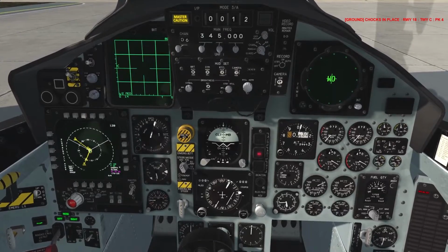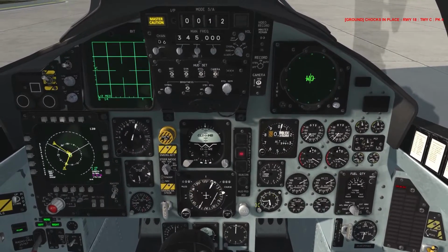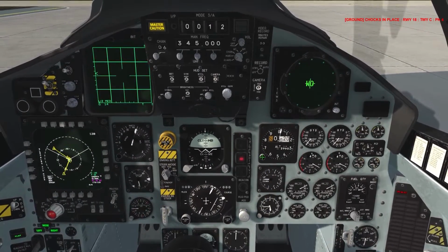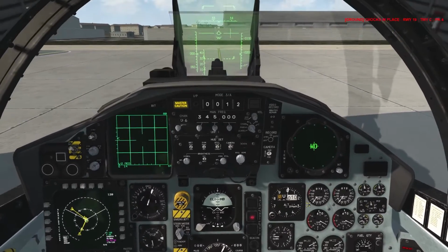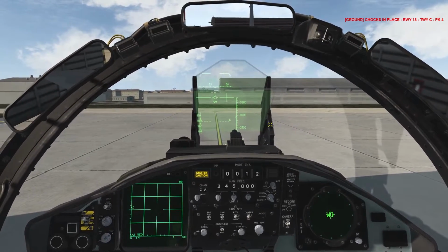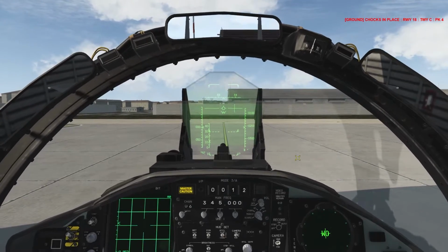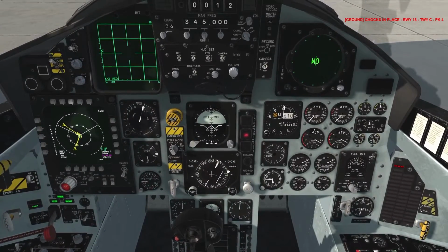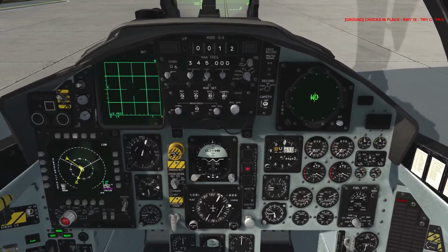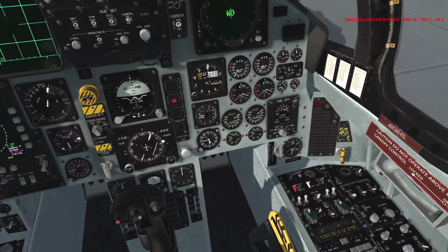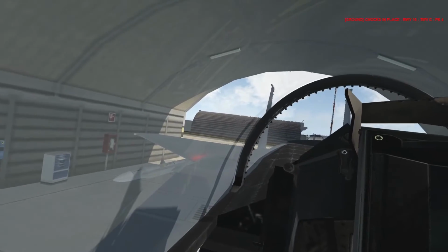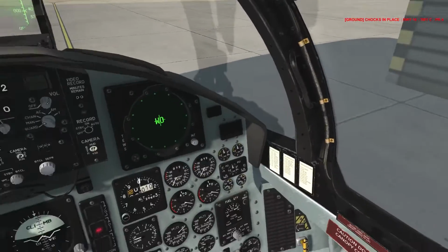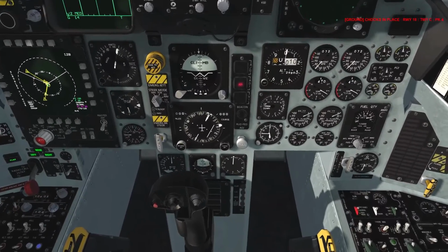Where are we? So altimeter's set. In this current build, maybe fixed before release, we do have a slight altimeter mismatch that's showing field elevation. Got negative 200 on the heads-up display at the moment. Ejection control safety lever armed. Again, we'll wait till we're outside of the shelter. GFS low light is out. Oh, speed brake still out. So let's just make sure that is fully in, which it is now.